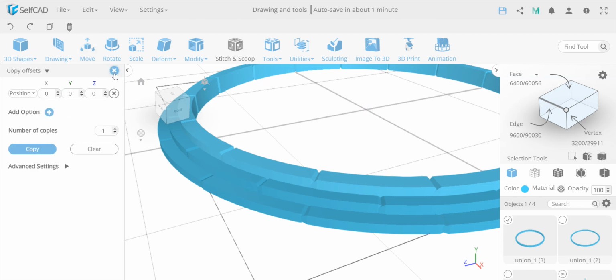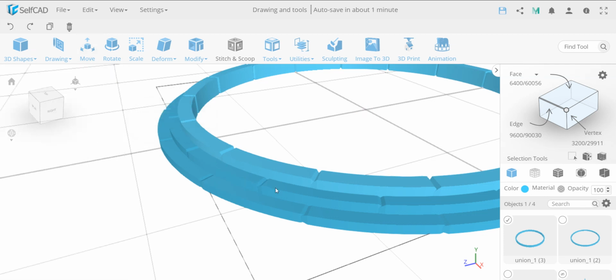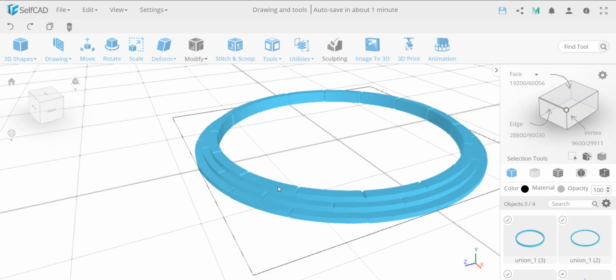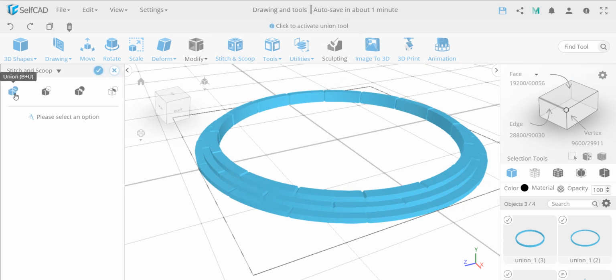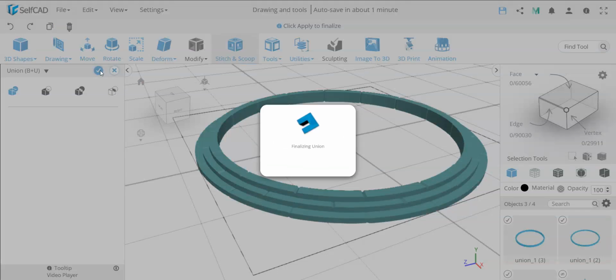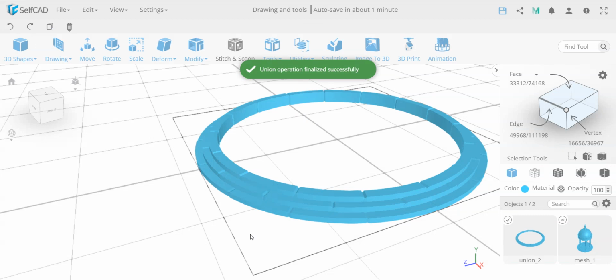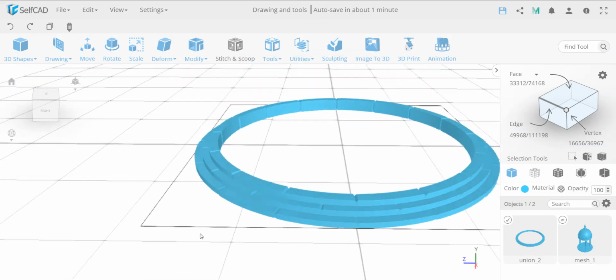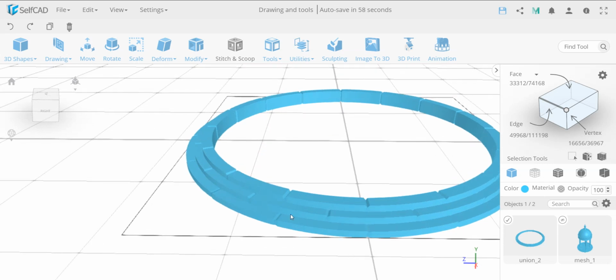So now I have all of these 3 objects. I'm going to select this and this. I'm not very happy that this is not thinner, but I think actually this looks nicer for this design, so let's leave it. And I'm going to combine these three, and as you can see, it processes very well. If you make them flush, you may sometimes get an error, and this is not a good idea. So that's why I'm paying attention, making sure to have variations.